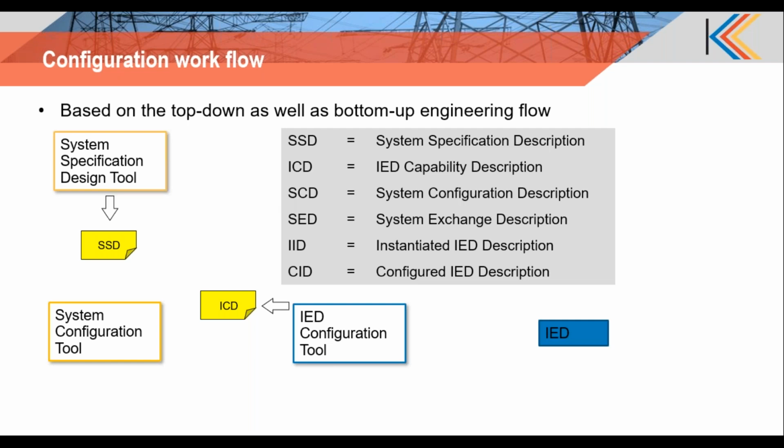Now, we have another tool called the system configuration tool. It has the capability of ingesting your SSD file and multiple ICD files representing each type of device in your configuration. One thing you have to remember about the ICD file is that inside it there will not be any names at all.